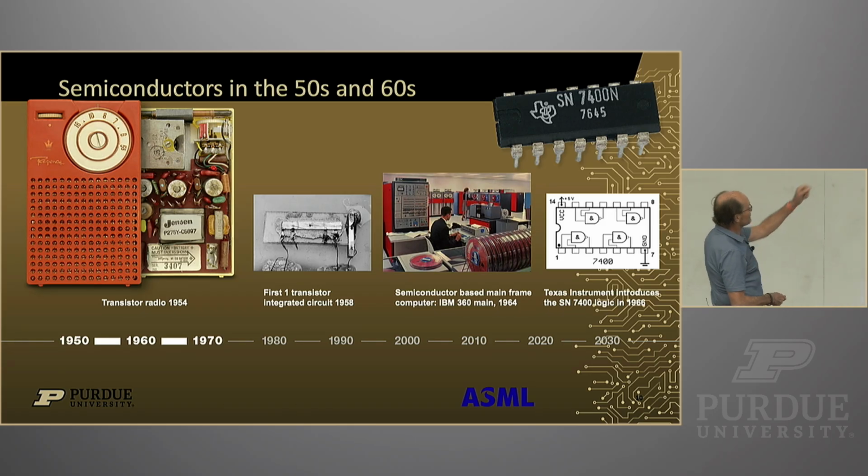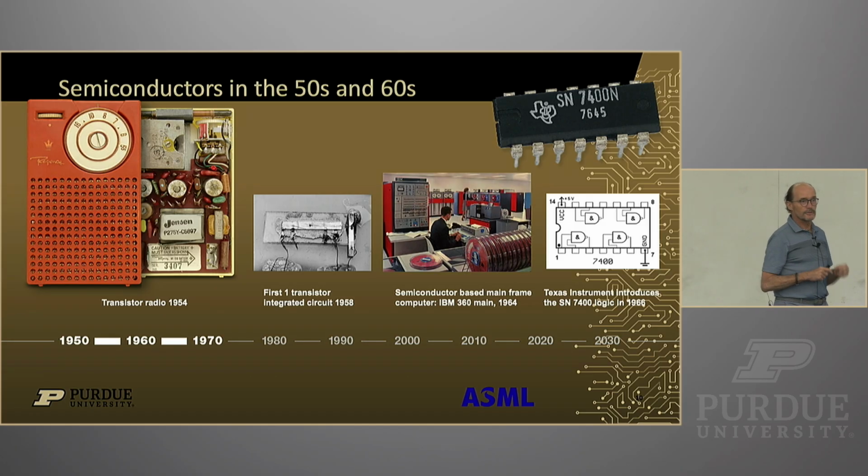You can also see that first computer from IBM. And you can see all the way on the right, the very famous, in my time, set of logic chips that Texas Instruments started to sell. And you can see here now that that had 4 inverters inside that one package. That was really exciting, because now you could build your own circuitry. 4 inverters. An inverter is a PMOS and an NMOS. That's 8 transistors.